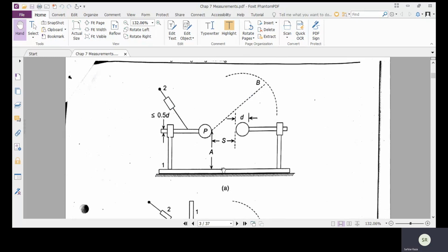So the other condition of this spacing is that the electric field which is going to be present here must not be distorted, its shape and its spacing over here and over here must not be distorted, from the external field and also from the surface. Otherwise we cannot get the accurate value of the electric field.